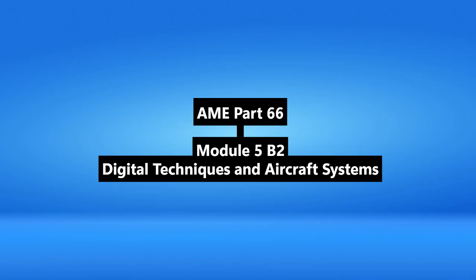Chaos? No, it's clever. It's a multiple source, multiple sink setup: everyone can potentially transmit. But it avoids collisions using a strict time-based protocol. Each terminal gets specific, pre-assigned time slots when it's allowed to transmit. Time division multiplexing, sort of. Exactly, but built into the bus protocol itself for collision avoidance.